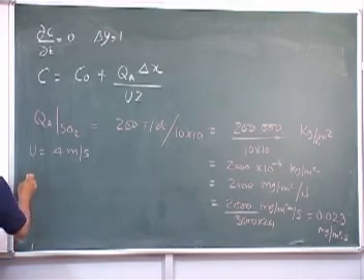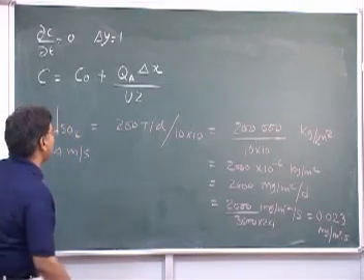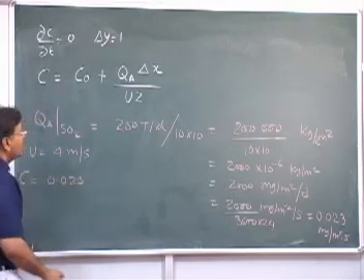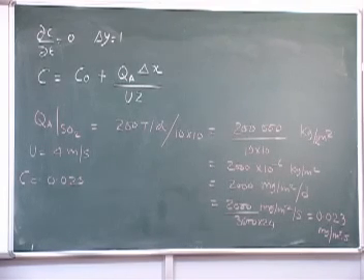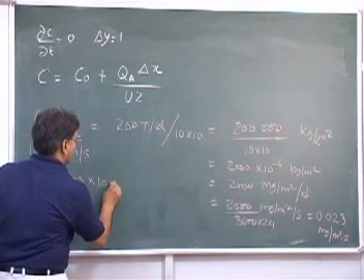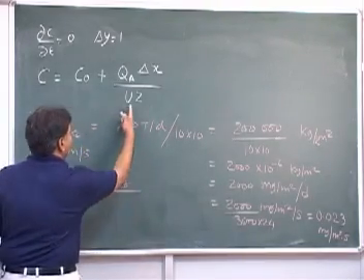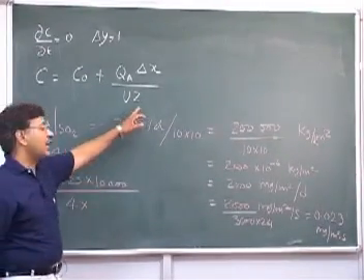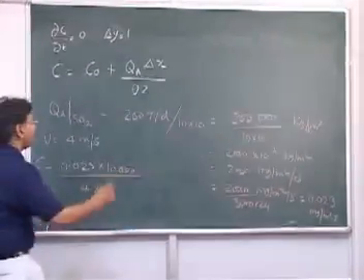Alright. So then I can simply find out C. Suppose initial concentration outside Kanpur, I assume that to be 0. So the QA is 0.023 times the delta X. That is the length of the city I can take, alright. That is equal to that many meters divided by 4 meters per second divided by the mixing height. I can take that as 1000 meters, that is typical that we discuss. So Z equals 1000.